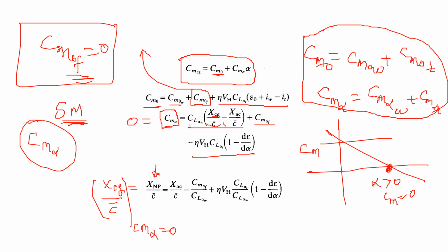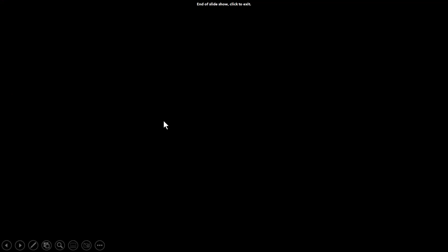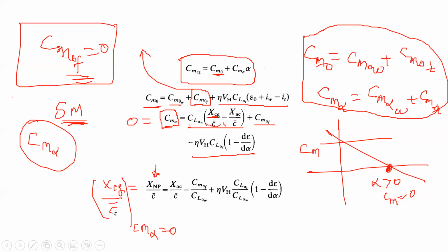someone was a pilot in our session last time. Is he still here? Yes, I'm here. Can you tell why they take care of weight distribution in the aircraft? They don't want people to sit in one area. They want to distribute the weight in some manner. That is predominantly to adjust the CG. There is a CG limit for every aircraft, both lateral and longitudinal. If the longitudinal CG is beyond the limit, then you will not have any control margin there. Exactly. And that's what we're talking about right now.